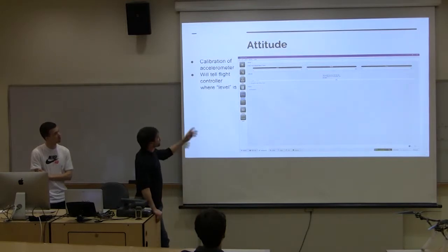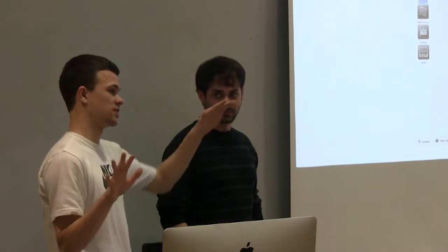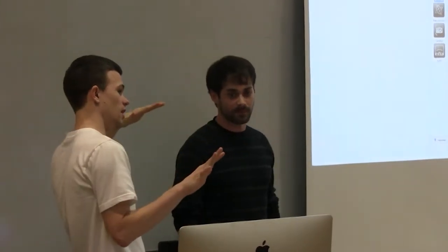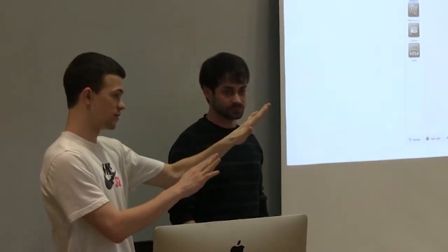And then calibration. Today we were flying the big quad, and what was happening is when you take all your hands off the sticks, it should stay level, but it was going one direction. So we were wondering if we calibrate the compass to be a little offset in that direction, that it'll stay level. So if you have those issues, you can maybe go into the attitude and adjust those parameters to fine tune your flight pattern.